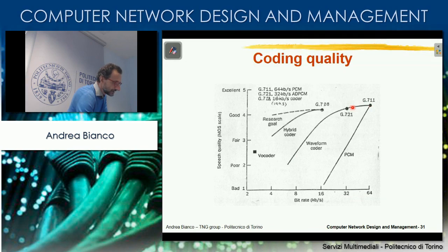This is the logarithmic PCM. You see that the MOS of this one is almost as good as the one of the PCM with 64 kilobits per second, and you see that the MOS of this coding, okay, with a reduced bitrate is almost as good as the other one. So in this area here we have 3 good coders which you can use for commercial purposes with their respective bitrate. Here we have a bad one. Here the same type of coder, if you reduce the bitrate, which is of course possible, you reduce by a significant amount the quality that you perceive.